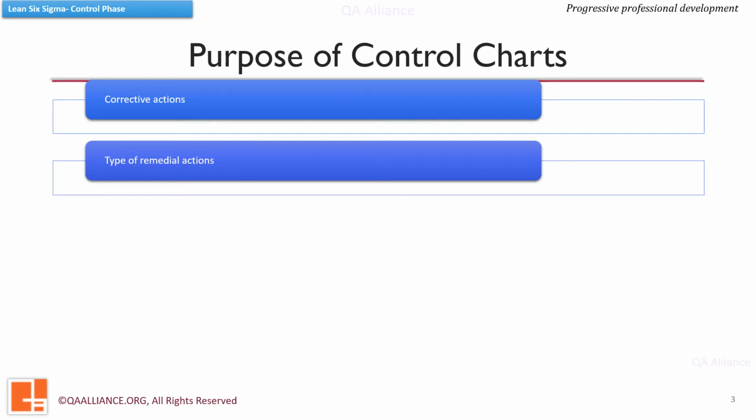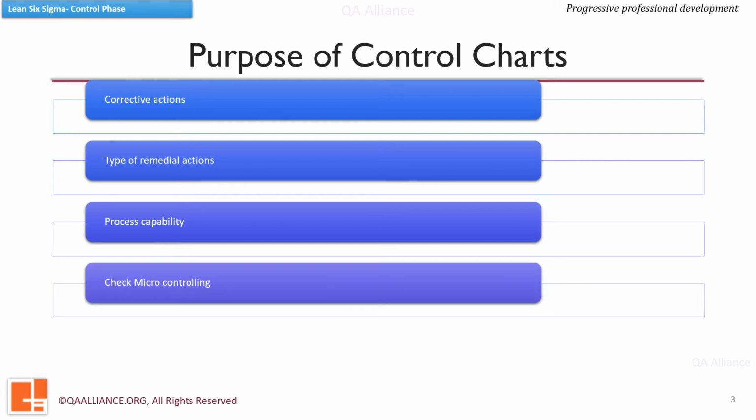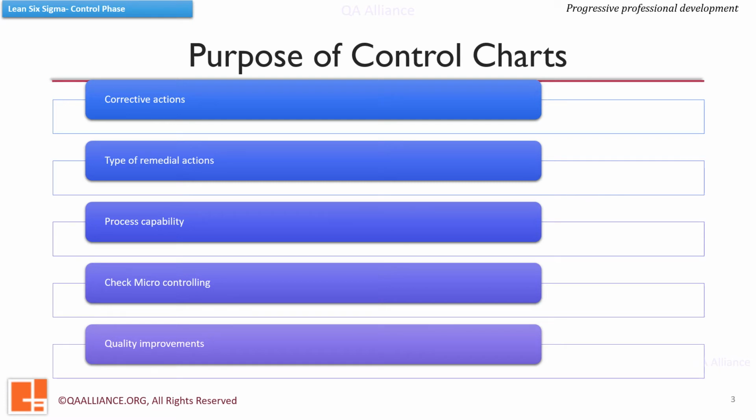As we know, capability analysis should be done only when the process is in statistical control. Control charts are thus used to assess if a process is under control or not. We also know that variation is a natural phenomenon. Over-control through frequent adjustments only increases variability. It is thus better to use control charts and make adjustments only when there is any indication of an out-of-control process.